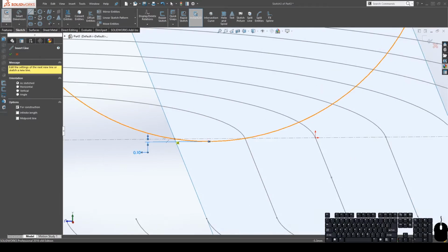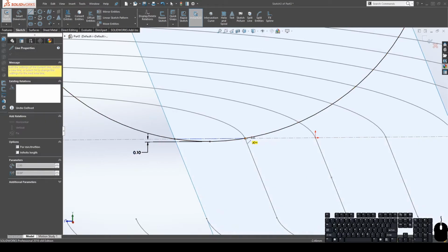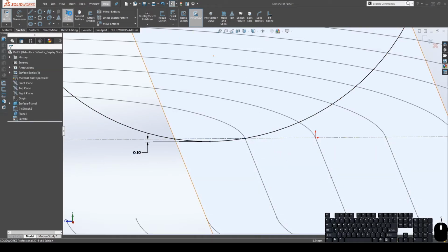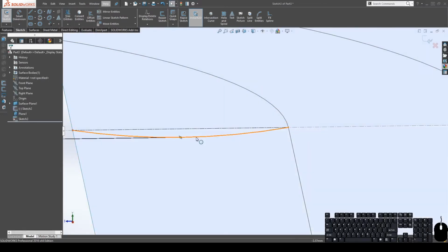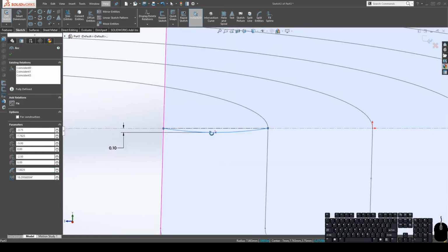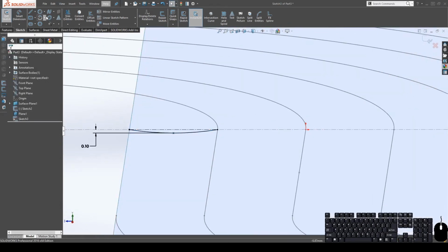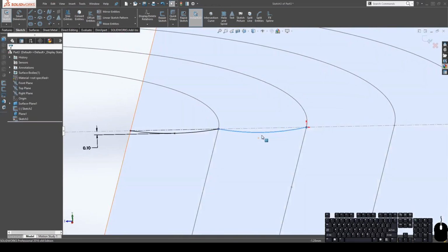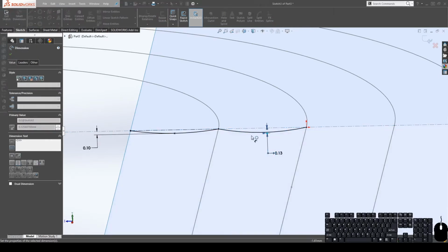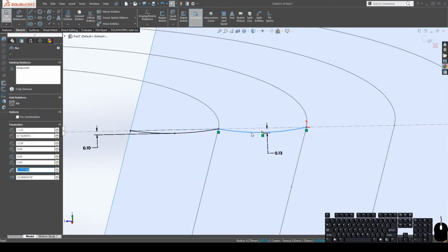And then let's create a center line between these 2 points and use that as the trimming. Okay, so we only want this little arc here. Another method you could have used is either a 3-point arc or a tangent arc. You could go something like this. That might be a little faster. Something like that. So that method is actually a little bit faster, but now you know multiple ways to do it.